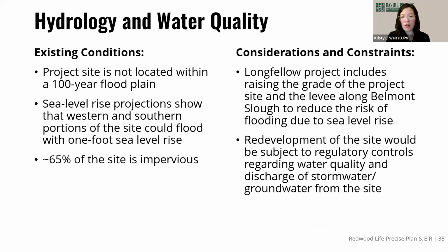For hydrology and water quality, we disclose that the project site is not located within a 100-year floodplain. According to FEMA, the project site is located within flood zone X. The project site is currently not subject to sea level rise flooding. However, sea level rise projections show that the western and southern portions of the site could become flooded due to a 1 foot increase in sea levels estimated in 2050.